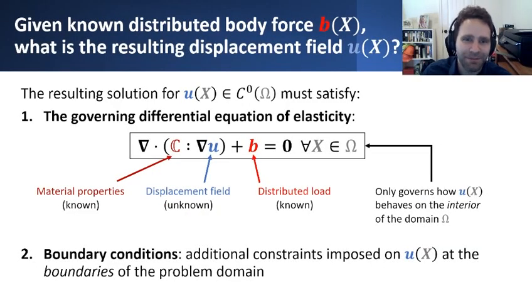A boundary value problem really is nothing more than a statement of seeking a particular solution for this unknown displacement field, describing how a body deforms under applied loads, subject to the conditions that it has to satisfy all of these different equations, all 15 of those previous equations, relating the strain and the displacement fields to one another, relating the strain and the stress fields through the constitutive law, and lastly, satisfying the governing equations of equilibrium.